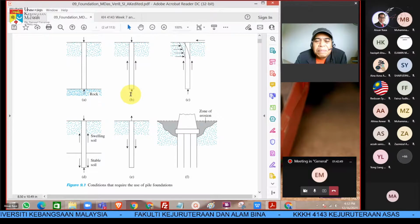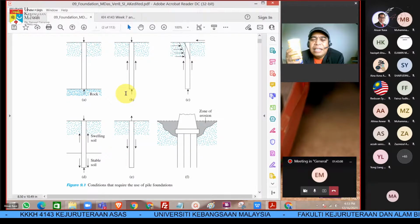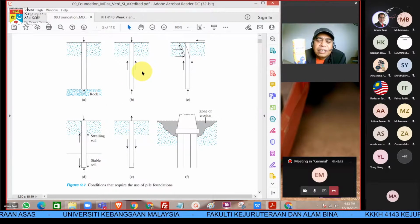But the actual structural load is taken care of by the skin friction along the skin. The friction of the skin here is handling the structural load. Okay, that is the second kind of pile foundation.